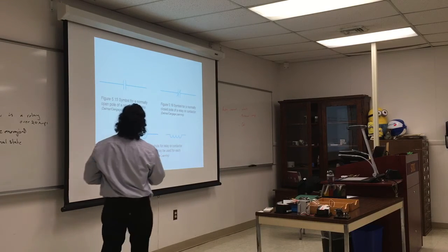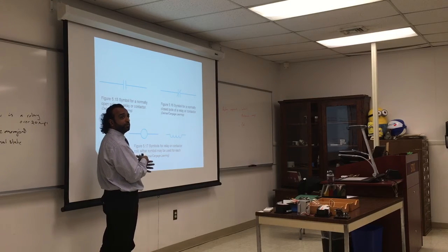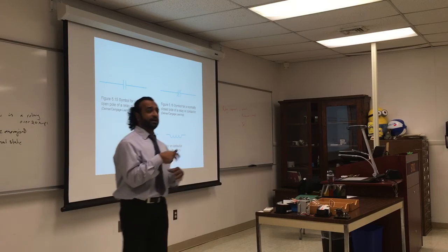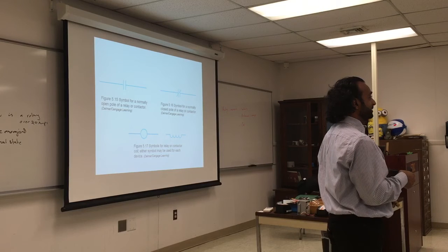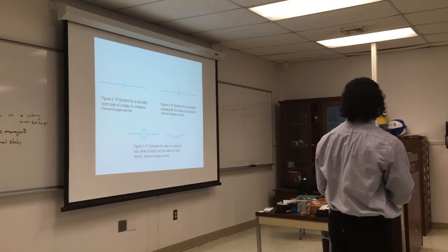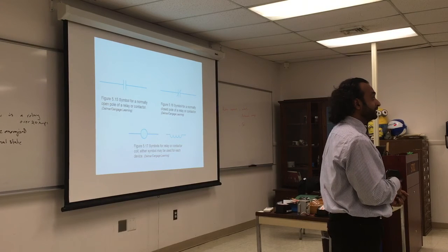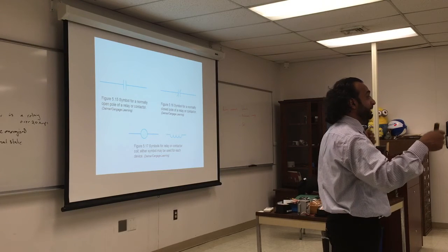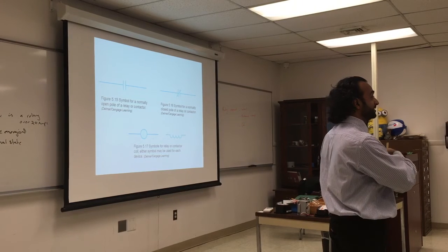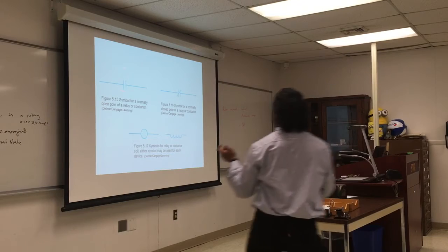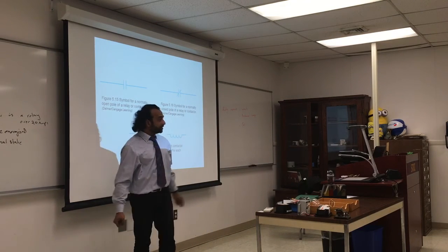These symbols are very common, but they could be different. What do you do if you are not sure what the symbol on that equipment is? If you look at wiring schematics and you see different symbols, check the legend. They do change it sometimes.